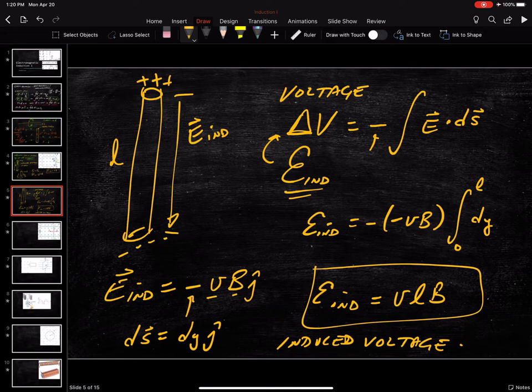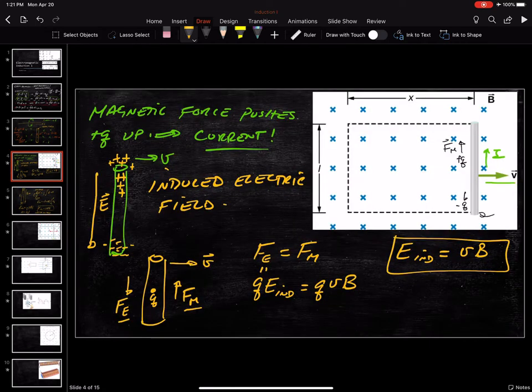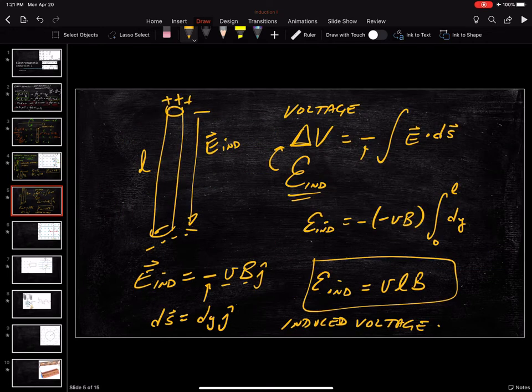Okay, so I've created a voltage across this wire by moving it through a magnetic field. And the voltage that I induce depends on how long the wire is. So a longer wire will induce a bigger voltage. Moving it faster produces a bigger magnetic force on these charges, and so the current is bigger, and so the charge separation is bigger, and so then you end up with a bigger voltage. Same thing for the magnetic field. And so in this case, you just end up basically with sort of a battery. You've kind of created a battery by moving this charge through there. You've put a difference in voltage, and if you choose all your numbers so that VLB is, say, 9 volts, you made a little 9-volt battery.